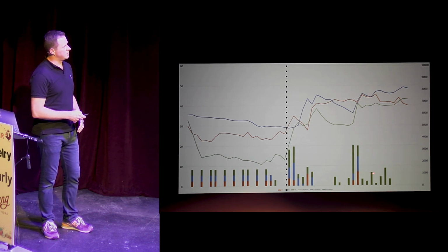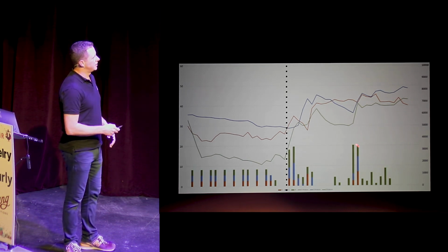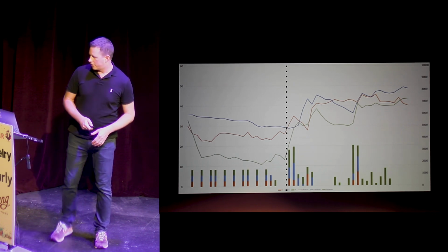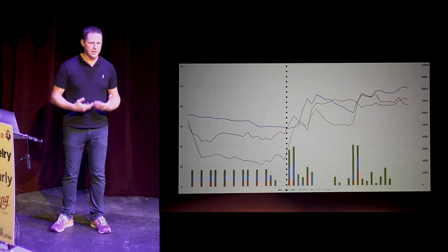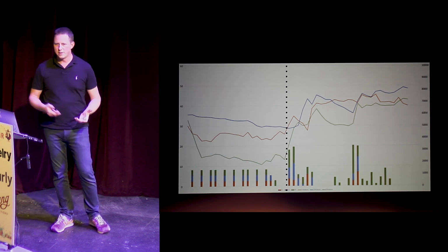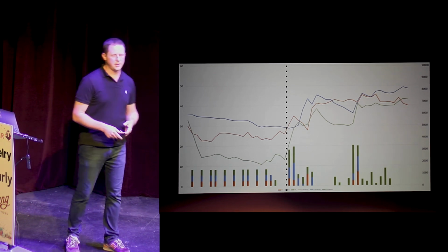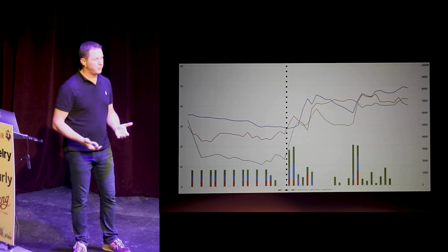This was a day we decided to move one of the sensors to a location that didn't look like it was getting rid of water, so it ended up deciding to sprinkle that sensor a lot. But all in all, it worked really well. Basically, I had ideas for lots of big logic. In the end, all it does is every hour it looks at the moisture sensors, finds the zone that has the lowest amount of moisture, and just runs that zone for a couple minutes. And that's all it really had to do.